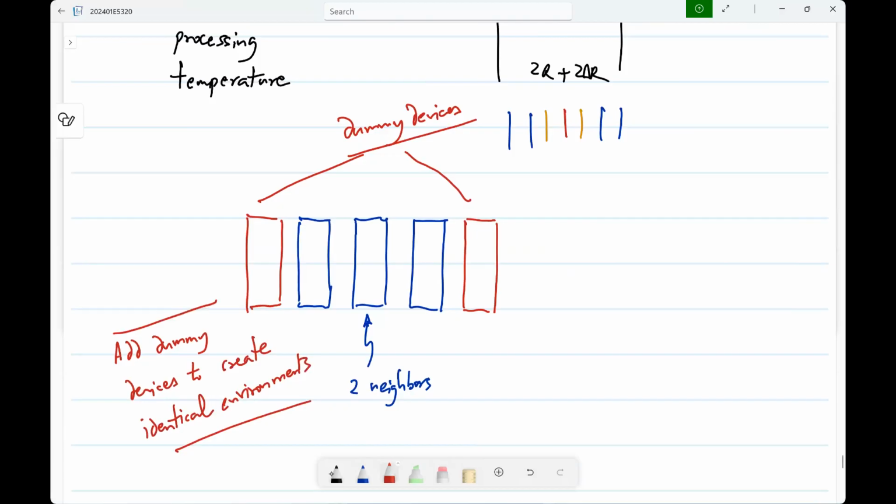This thing about systematic mismatch, there is not much to calculate or anything, but these are things that you need to know. That is, when you start doing design, that's when it makes sense. For now, these are just facts that you have to take. Because in principle, when you're drawing circuits, you can draw it any which way you want. But when you're physically making it, you need to observe symmetry, maybe common centroid, add dummy devices, etc., to minimize this